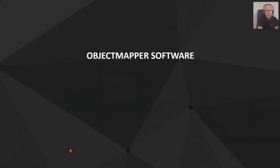Okay, so once I've completed the data collection, I would stop the project and we can then upload that data onto a memory stick, onto the USB, by the USB port on the back of the GPR, and then we can transfer that to the PC.